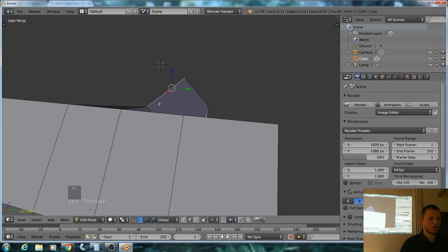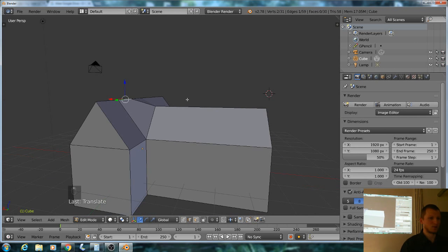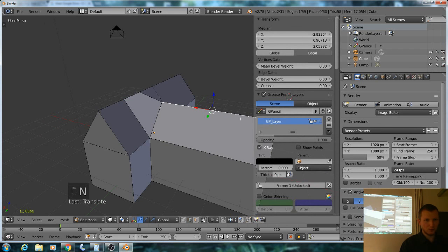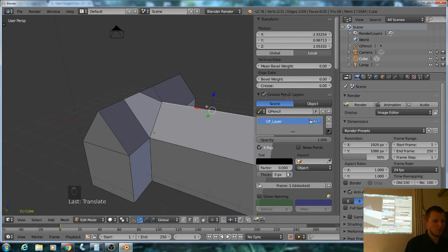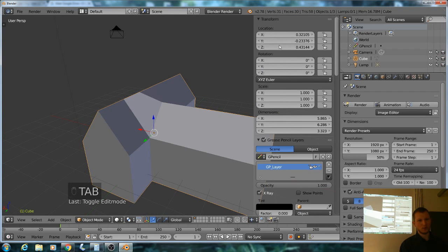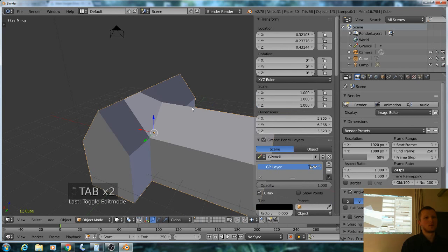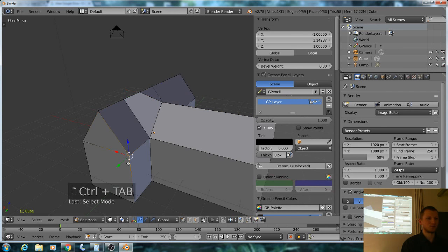I have to check what the height of this part is, and then I can input that height for this part also. And if we come back to this right side panel, press the plus button, the content has changed a little bit. Before I had these 4 transformations, and now I have only 1, and it says median or just vertex.